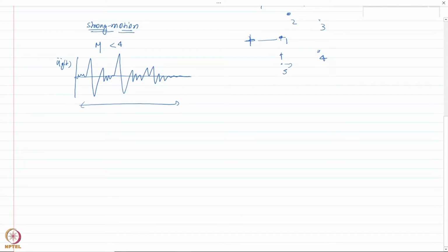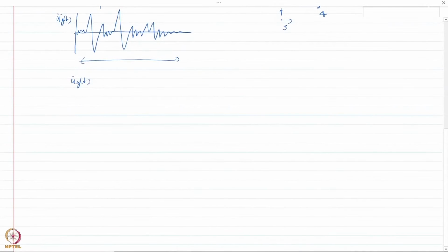the accelerograph would provide you basically the acceleration history, which would be in terms of time and then acceleration, which might be expressed, let us say, in units of g. So something like this. If it is a uniform interval of, let us say, 0.02 second, it would be something like this. This is just a fictitious value. So it would give you basically discretized values of the acceleration at different time instances.